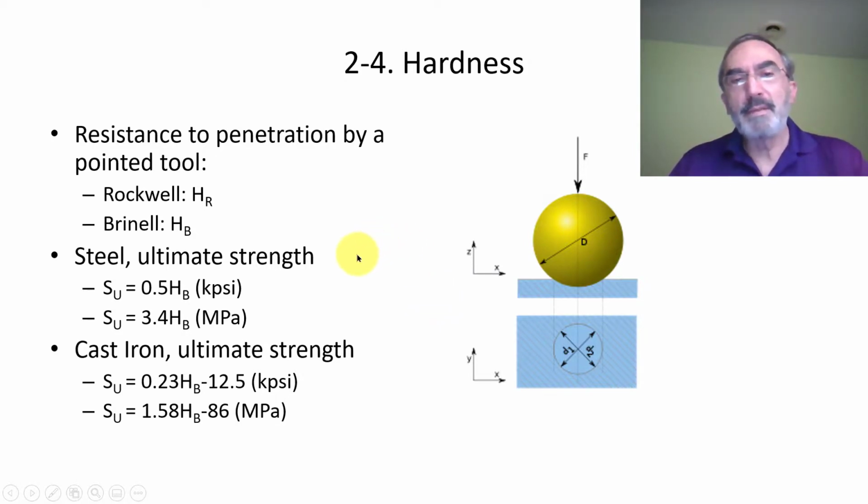Now, people have done hardness together with other tests, say ultimate strength, which is a tensile test. It's not so difficult, but it's destructive. You have to cut a piece of the bridge, bring it to the lab, and break it, like in the video that I asked you to watch, to find the ultimate strength. Then you have data of ultimate strength and data of hardness for different materials, let's say various types of steels, and you feed that data and do a correlation. You say, I can approximate, I can guess.